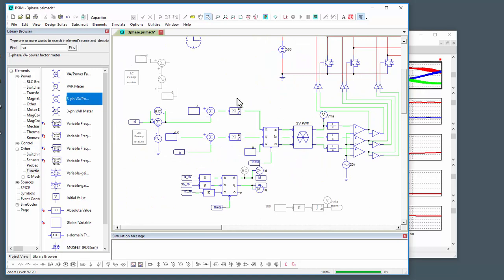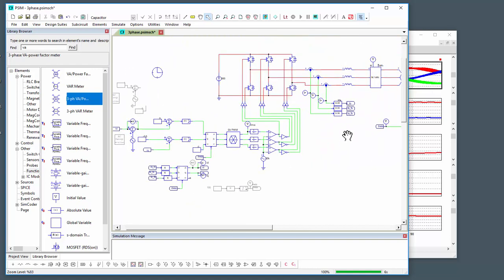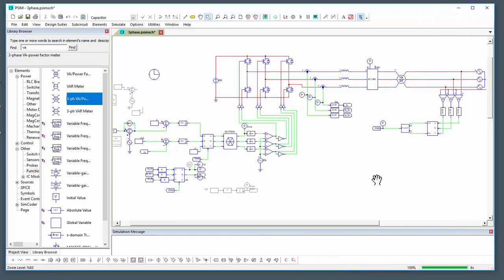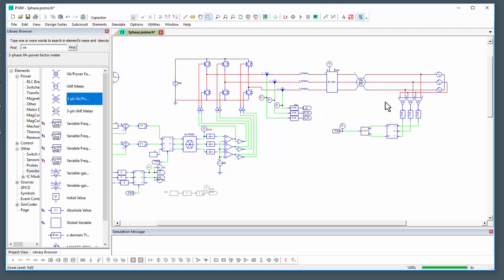So that's it for this tutorial video. This is a 3-phase grid-like inverter with DQ control, where the D and Q references allow us to pass power back and forth between the two supplies of either real or reactive.